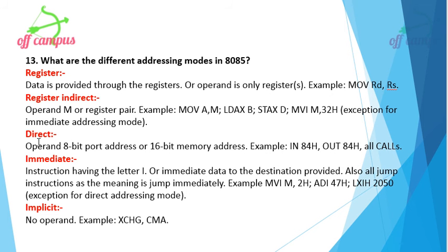Then coming to the direct addressing mode. What is direct addressing mode? The operand is an 8-bit port address or a memory address. What will be the operand? An 8-bit port address or a 16-bit memory address. That is given as direct addressing mode. IN 84H, OUT 84H, and all CALL instructions come under direct addressing mode.